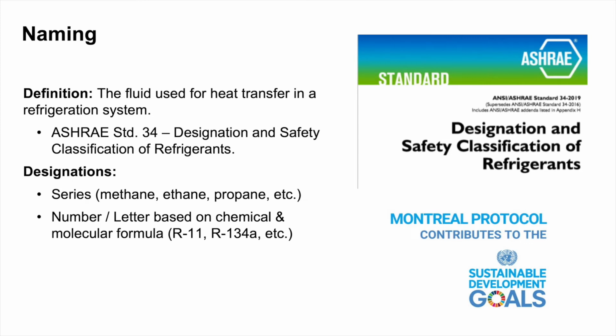There are many different types of refrigerants out there that we can use as applied to the HVAC and refrigeration industry. But basically, the refrigerants are the fluid used as the medium for that heat transfer in any refrigeration system. ASHRAE Standard 34 is what designates the safety classifications of refrigerants. It's essentially the Bible of refrigerants, and every attribute about them is identified in standard form.